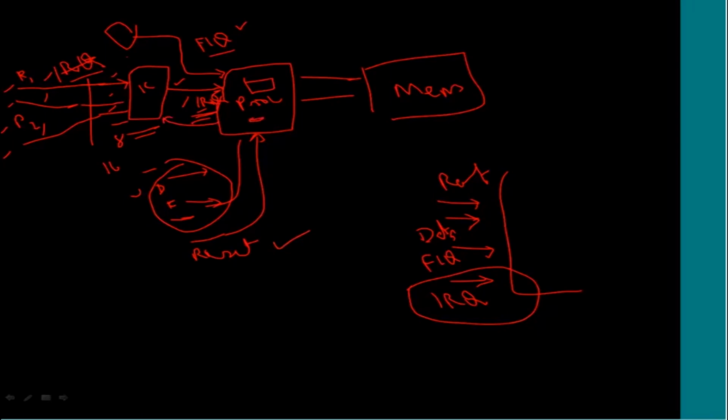And you can decide selectively to enable some interrupts or mask some interrupts, and then give different priorities to them, and you can even configure it for level trigger or edge trigger. Those are so many things which are there to configure this interrupt controller, how it has to process the input coming from different peripherals.